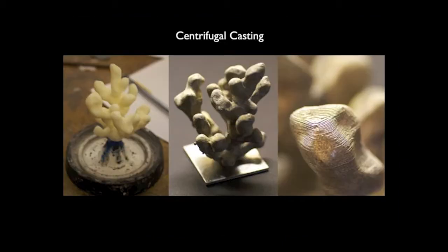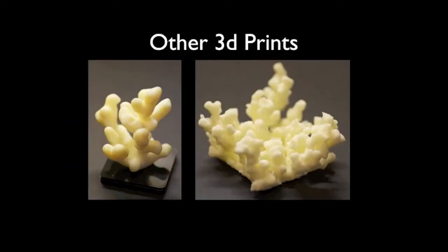This process involves pouring a plaster-like substance around the model, burning out the plastic, and then inserting molten aluminum using a centrifuge. The model on the right has a square base, which is more representative of a real heat sink application. The model on the left is a much higher quality print of the first structure. This is an animation of the simulation running in real time.